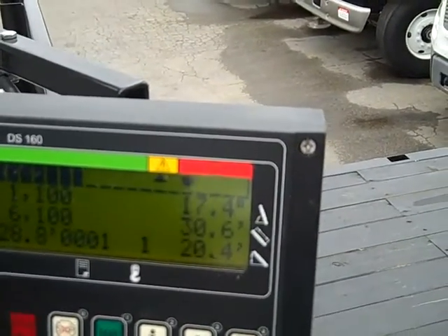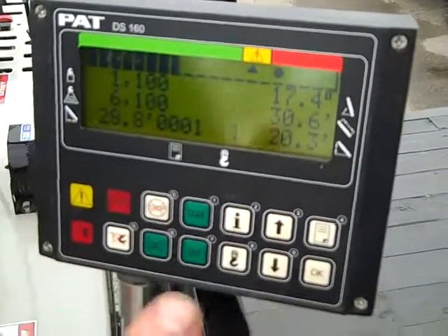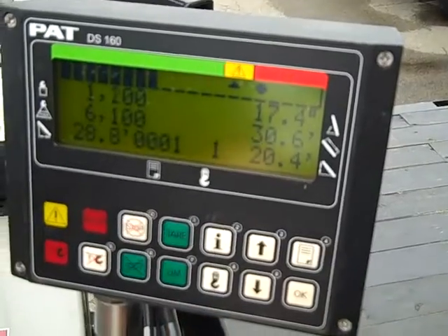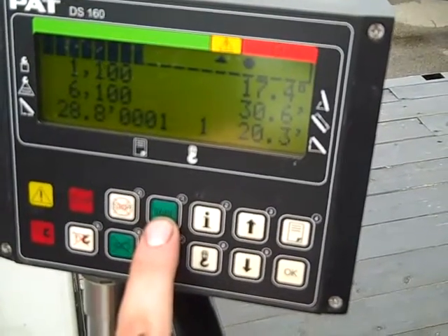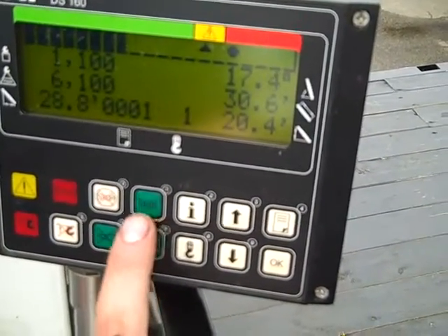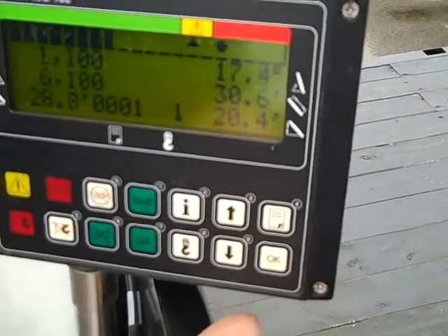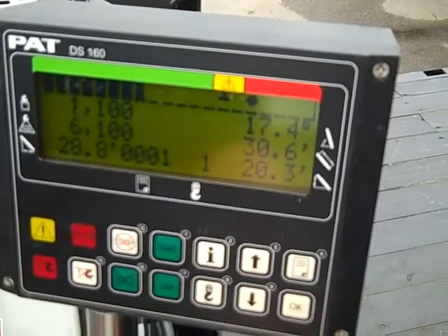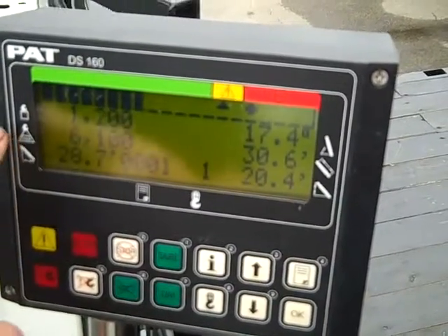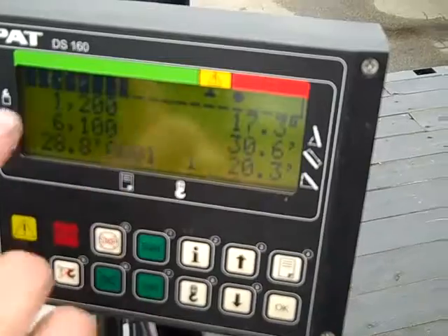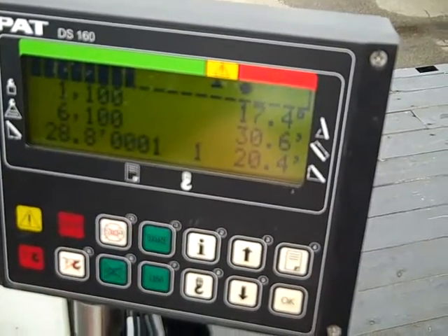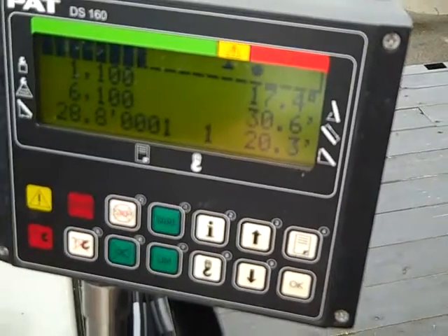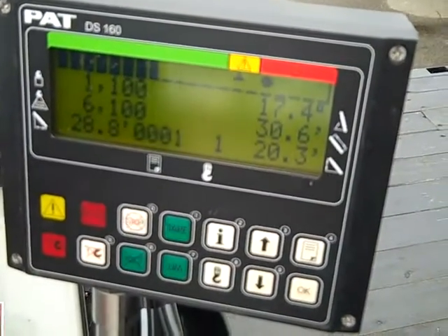Okay. Now there is also the tare. If you are lifting, let's say, if you're using a hopper or a set of forks, perhaps? Set of forks. You can lift the forks. The forks will have a weight of, say, 500. Your weight will show up here on weight lifted. You can hit tare and it will re-zero it and it'll only weigh what is on the forks. Okay. And does that go away when you release the tare button? Yes, you just re-hit it and it'll reset. Okay.